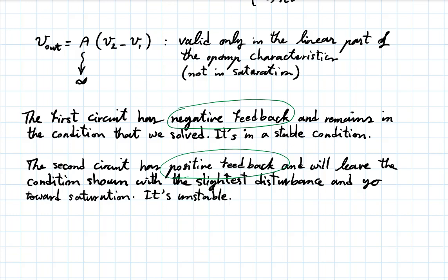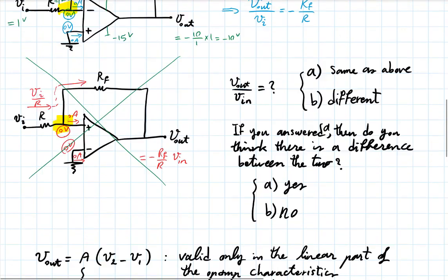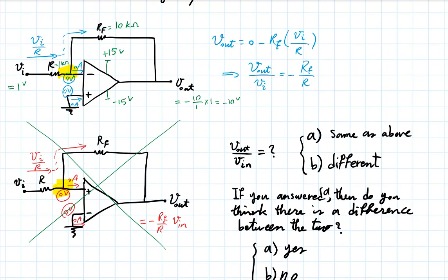But I'm hoping that this gives you a feel for what can actually happen, and the reason why we connect our feedback path to the negative and not the positive side of the op-amp. This also reminds us that when we get a circuit, in general, there's no guarantee that it's been built properly. We have to consider whether there is proper feedback to make it stable.